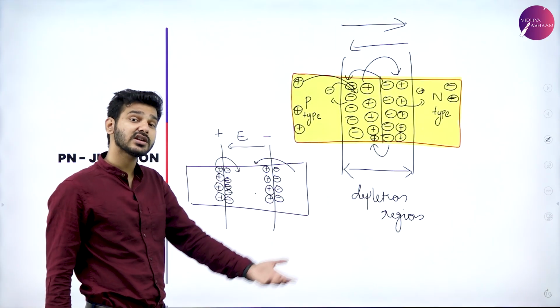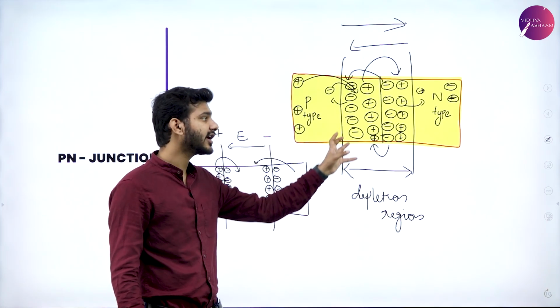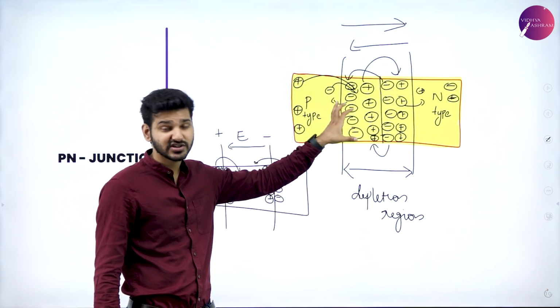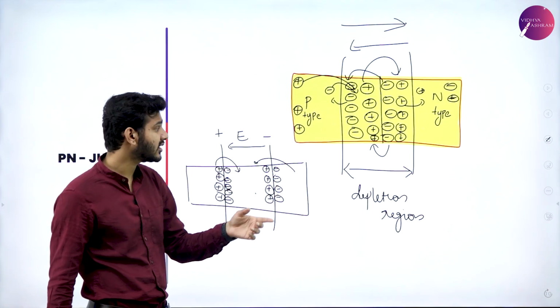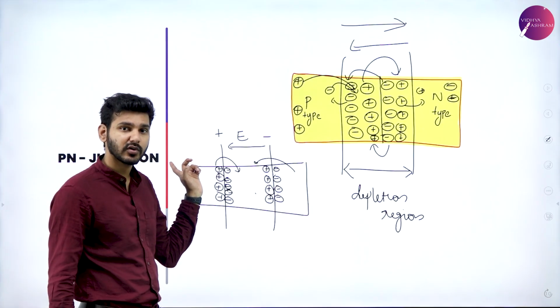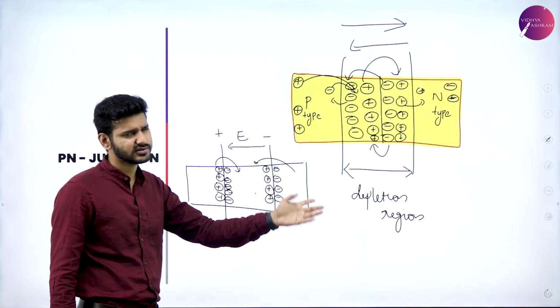That is a different type of current known as drift current. So stray ions entering this depletion region will be accelerated in the opposite direction. Again, that is only because the electric field will be in one direction. If any stray ions enter, they will be accelerated in the opposite direction. That's it.